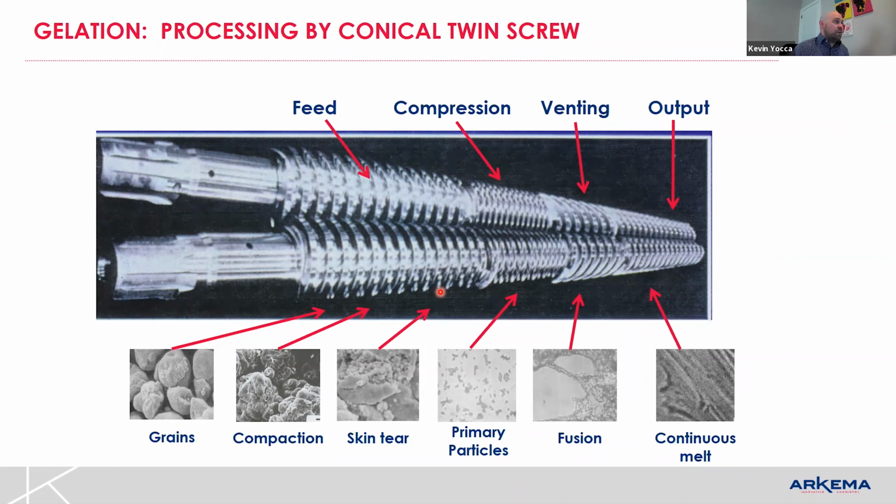I always tell folks, don't underestimate how you can use it. A simple Brabender test, just to test where your fusion peak is, where you see any kind of degradation beginning, how much compaction, what your bulk density looks like. Okay, bulk density is important.